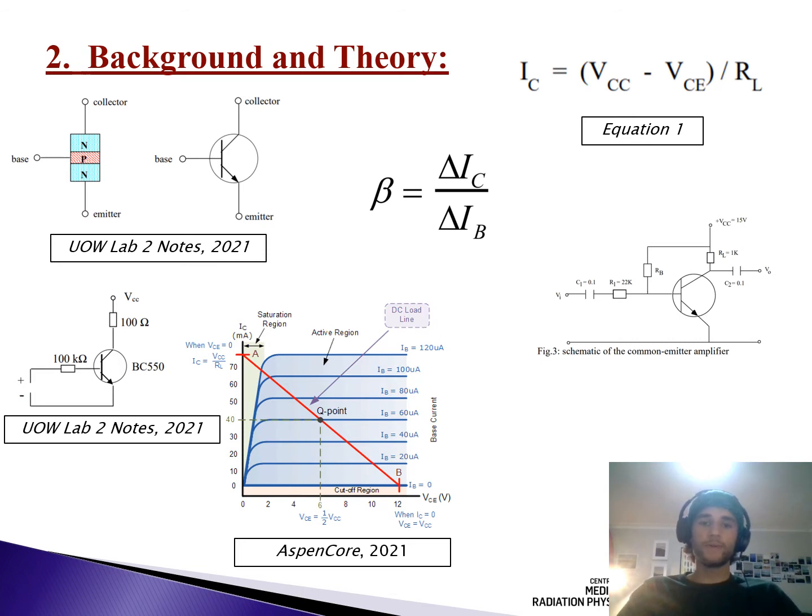Also, it's important to note that capacitors are highly effective at blocking DC and therefore allow a signal to pass without interfering with the DC bias of a transistor. Therefore, by adding a capacitor at each terminal, the desired AC signal is able to pass whilst the unwanted DC signal is blocked. The coupling of these capacitors is therefore highly effective whilst adjusting the level of base current.